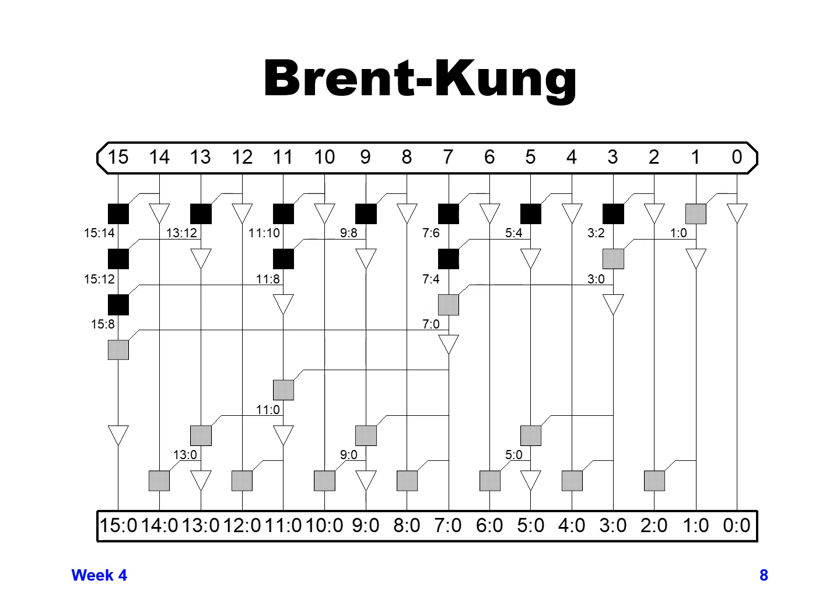If you look at the highest order bit, 15 there, you can see it takes one input for the first 2-bit group from 15 and 14, and then for the next group, it takes the 13:12 group combined with its 15-14 group and gets 15 through 12. Then it takes the 15 through 12 combined with the 11 through 8 group and gets 15 through 8, and then combines the 15 through 8 group with the 7 through 0 group, and you can see we've gone through 4 of those stages for 16 total bits,